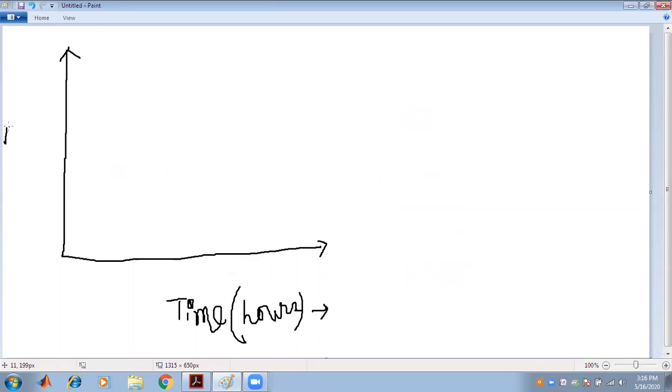In the problem it is given in megawatt, the load along the y-axis. So let us take some scale division. The scale division is 2. It is totally dependent upon you how many scale divisions you make to get a simplified load curve.